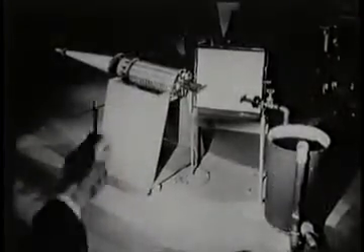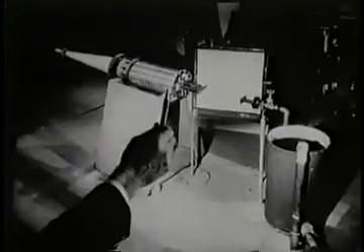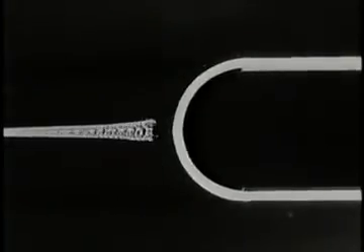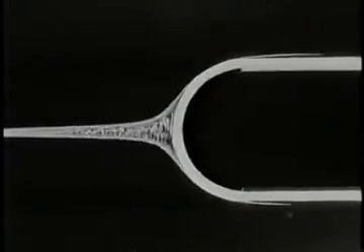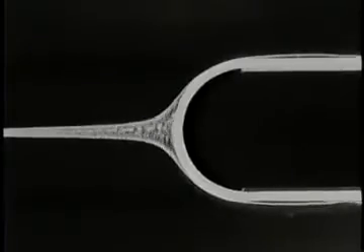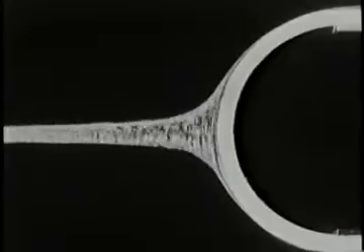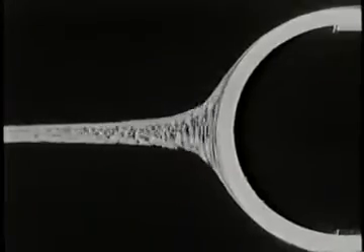A very large reservoir supplying a flow to a duct system is itself a stagnation region. Here is a streaming flow past the blunt body with a central stream tube marked by hydrogen bubbles. The widening of this stream tube tells us that the flow is decelerating.